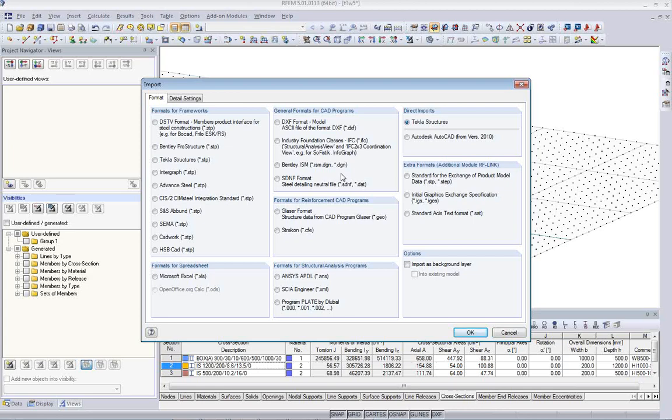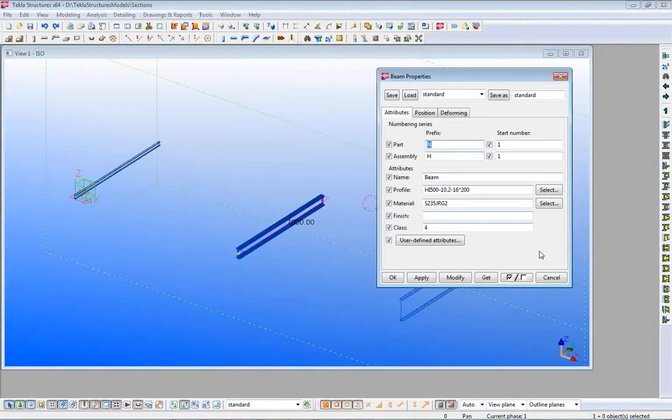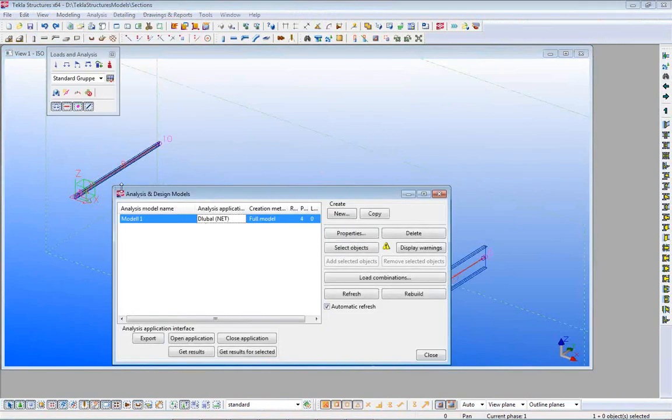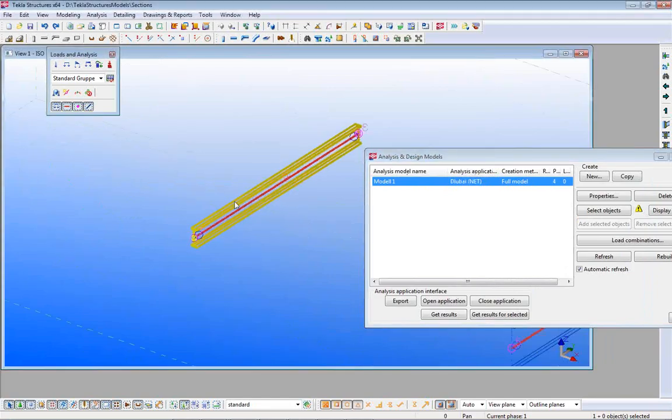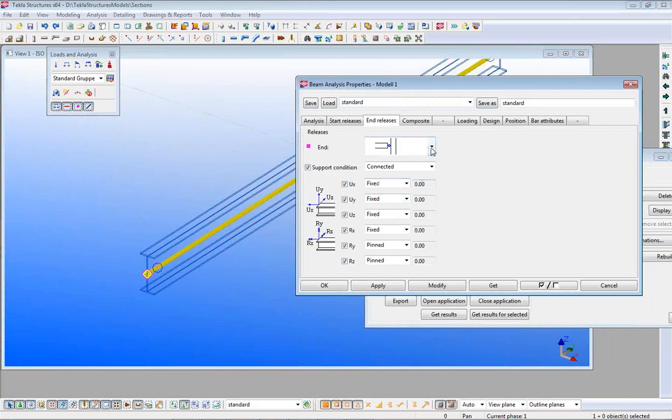Can I use springs as a release in Tekla? As I said, in Tekla you need to have an analysis model. You can set up releases here and also spring constants. They can be, for example, a spring. And if you have this spring constant, then we also import this spring constant inside our analytical model.